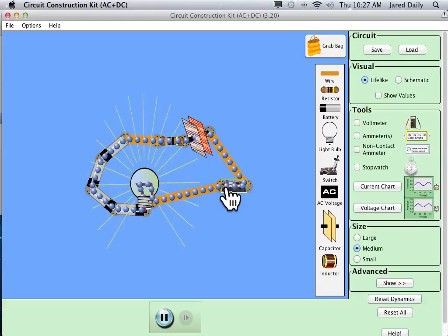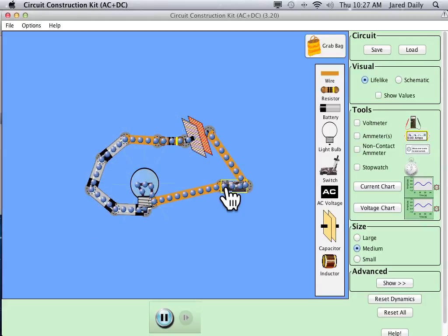And it starts out, the current starts out going really great because there's no charge on the capacitor, and charges can run towards that capacitor as fast as they want. But as soon as charges start building up on that capacitor, they start resisting the current. They start pushing back against any other charges that go there. And eventually the charges stop going to the capacitor because it's full, right? So it starts out really bright, the light bulb, and then it goes dim, dim, dim, dim. In other words, the current starts out really high, and then it dies off as the capacitor fills up, right?